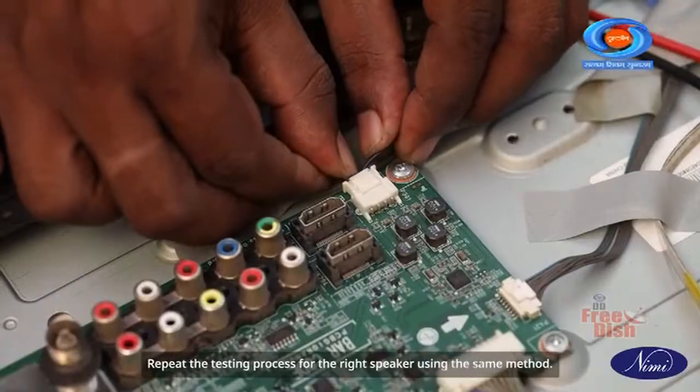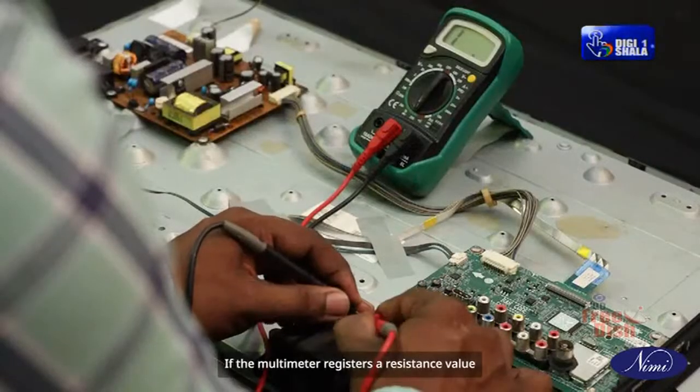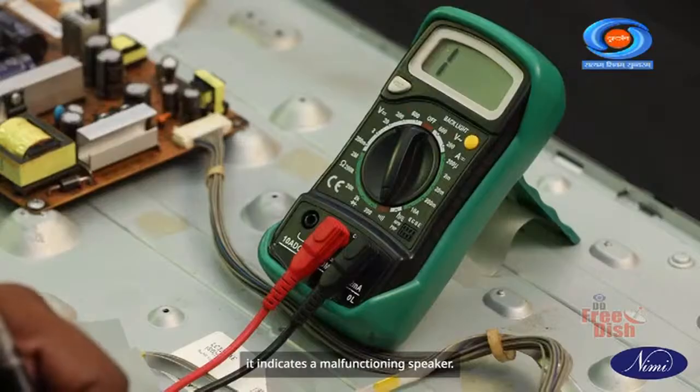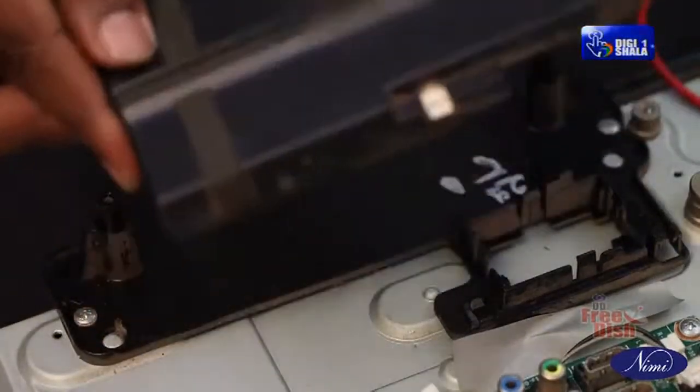Repeat the testing process for the right speaker using the same method. If the multimeter registers a resistance value outside the acceptable range, it indicates a malfunctioning speaker. In such cases, immediate replacement is necessary.